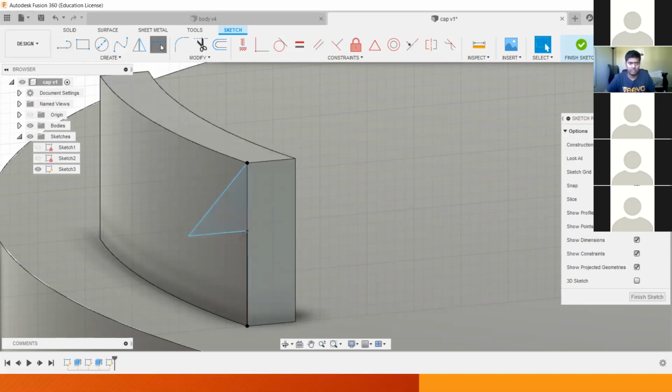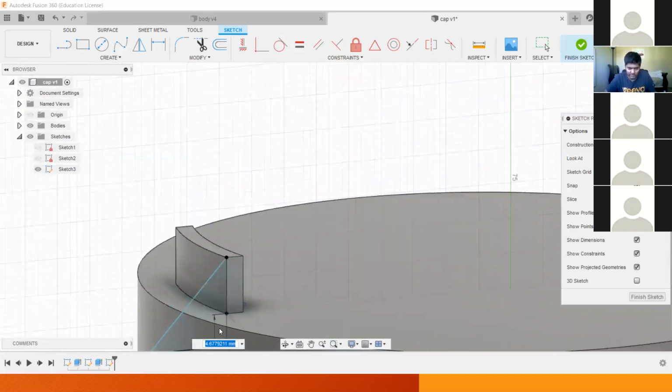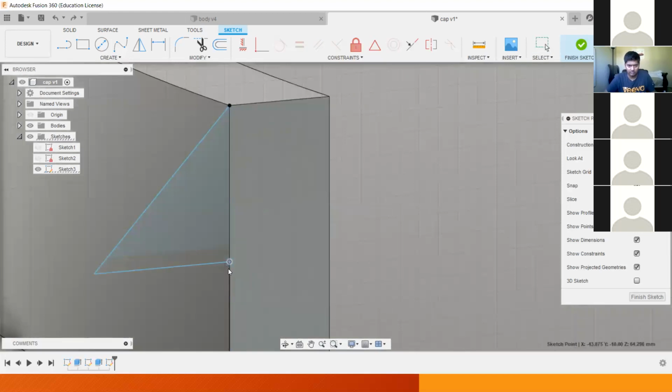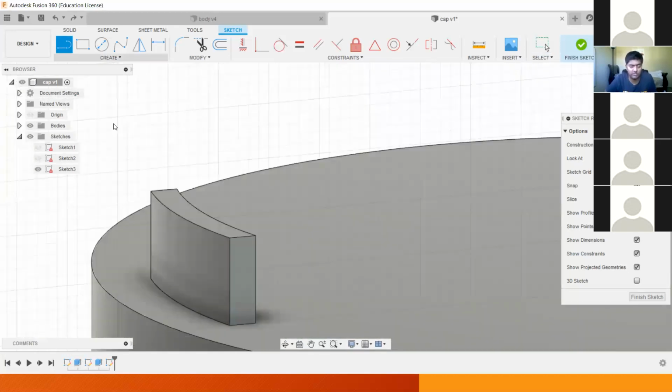And we're going to use sketch dimension again. And hopefully this time it's behaving. Okay, sometimes sketch dimension is annoying to use, so I'm going to just leave it. I'm just going to specify from the get-go 5 millimeters and not do sketch dimensions.